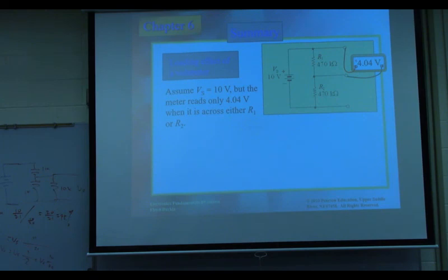So if this one equals 4 on the top, what is the voltage on the bottom? 6, right? It needs to be 6. But you measure it, it is 4. Voltage source is trash. What happened? I will leave this one as a question. Internal resistance?